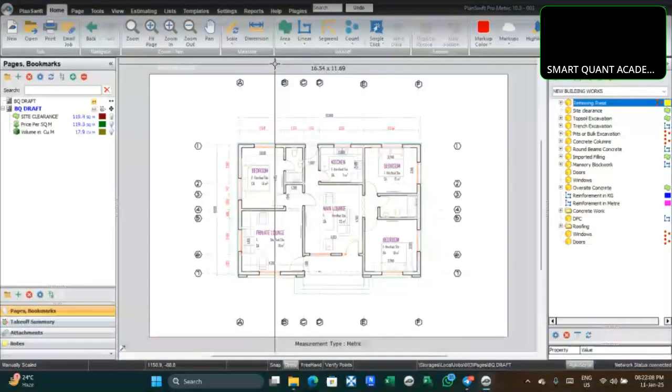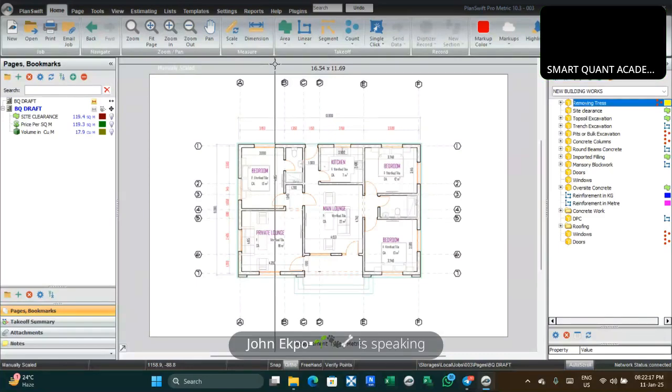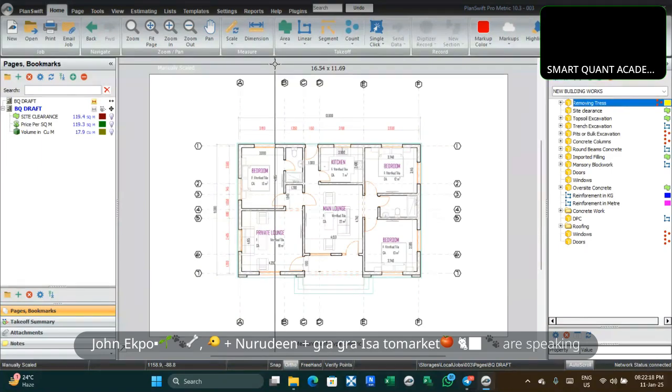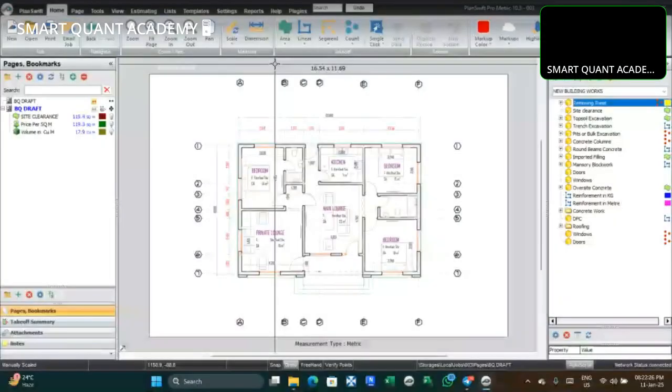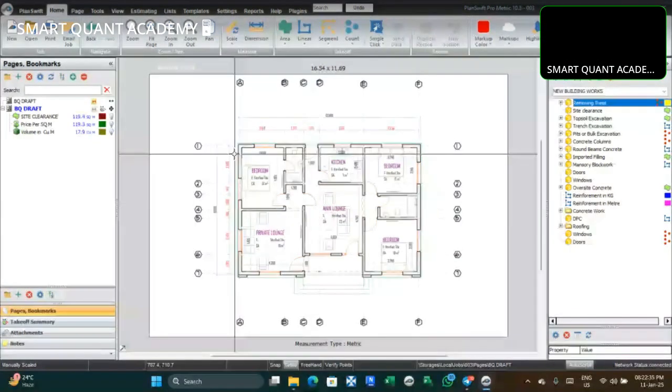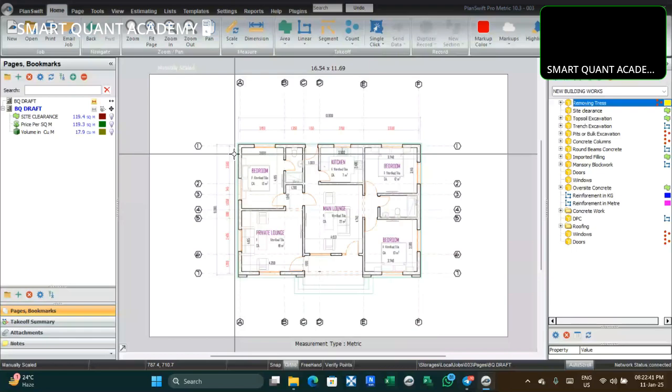Okay, you are trying to get the height of the king post, if I understand. I get your point. We are speaking of two different things. Normally on site, in a situation where the laborers don't know the pitch, they divide the width of the building and use it as the king post. Whatever the angles give them, they don't care. They just get the height of the king post and move on.